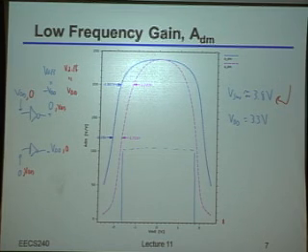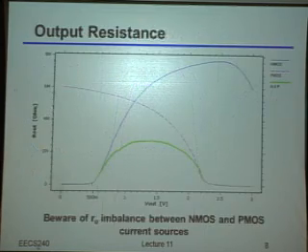Now, the problem with that is that, let's say this swing is not large enough. You actually want to go ahead and improve it. If you just look at this plot, you may not be able to tell which transistor or set of transistors is dominating your overall swing characteristics. Because of that, you'll typically want to plot not just the net gain curve, but split things out to look at the NMOS and the PMOS devices independently. So for example, this blue curve here might be the RO of the NMOS devices as a function of the output swing, and this pink curve here might be the PMOS output resistance.